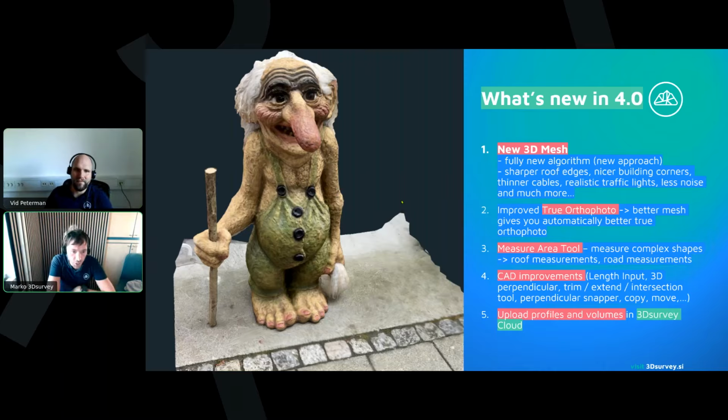If a construction machine, vehicle, or other materials were in the way during the recording, they will be included in the reconstruction in the 3D mesh and orthophoto and in the contour lines. Then I have to recalculate everything again after removing the interfering objects? Okay, you don't need to recalculate everything.